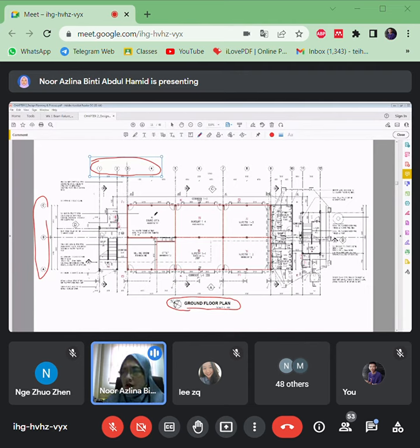So it mentioned here, this is a dining area. Okay, this is a nursery, I think. This is the corridor, toilet, and everything. This information is very important for us as structural engineers, because from these labels, from this space, we know what the functions are. We know what the QK that should be applied on these slabs is, right?